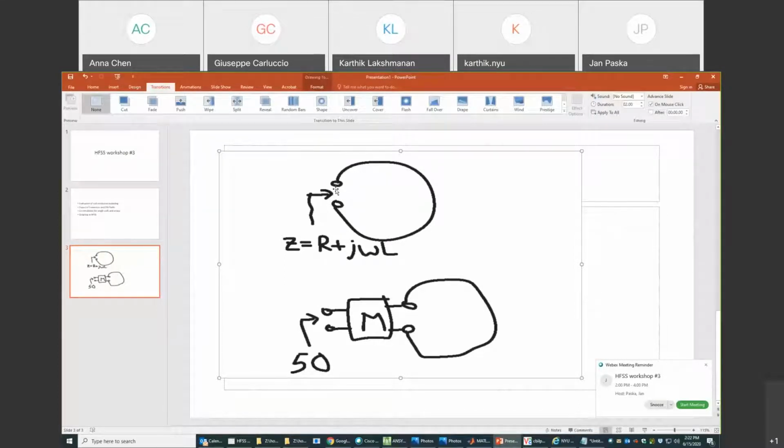But actually what we need to do in the experiment, every MR coil is usually matched to 50 ohms. And this we achieve with a matching network. That matching network transforms the coil impedance, which usually has a small resistance and a high imaginary part, and it's usually inductive. So it transforms this impedance to 50 ohms.